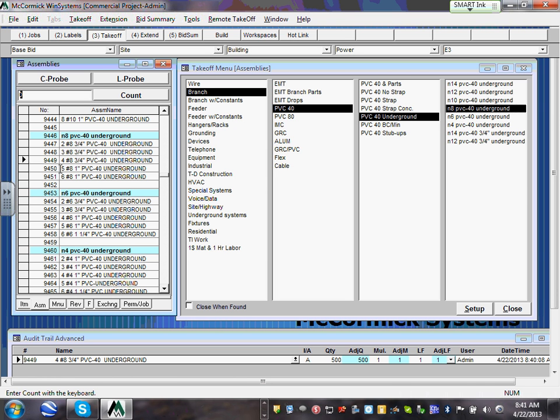I have 5 conductors in an inch. Here's 4 conductors. Oh, these are number 6. If you decide to use something different from what the software gives you, your only option, guys, is to take it as a wire and a conduit, a separate conduit and a separate wire. I'll show you how to do that one. Conduit and a wire, not as a branch circuit.